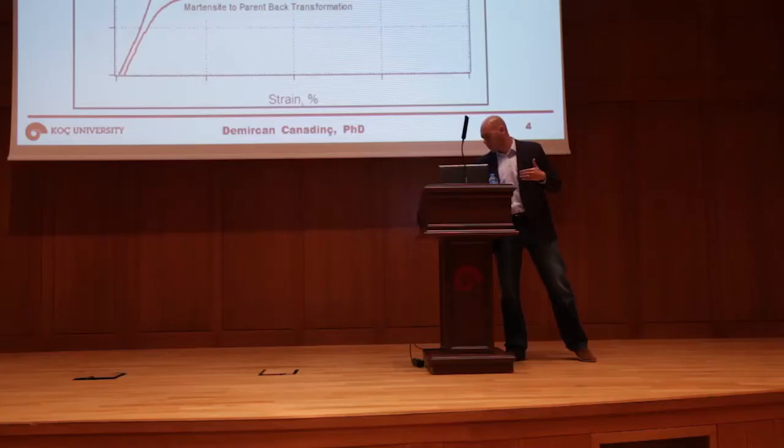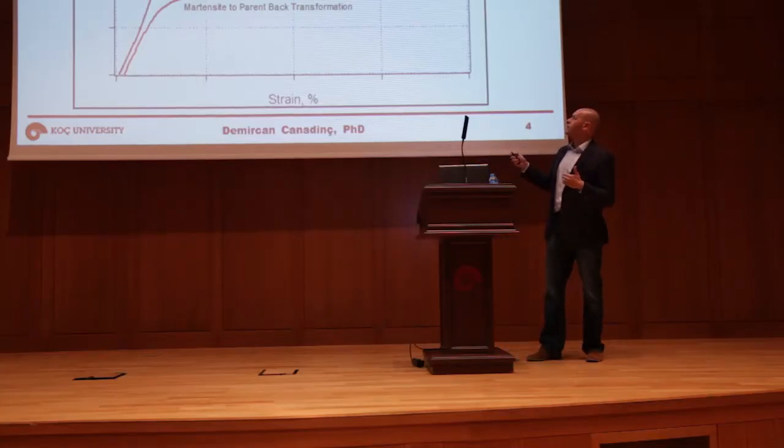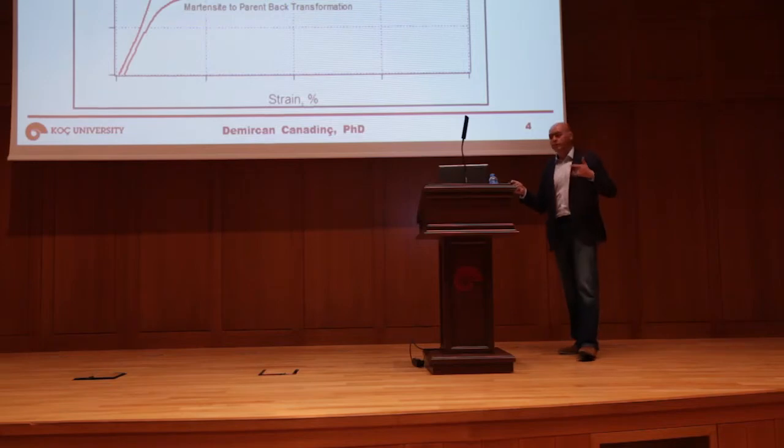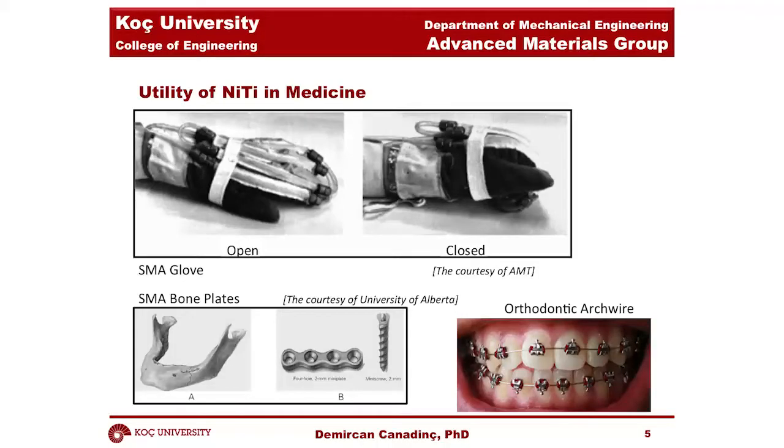However, due to the pseudoelastic property of these materials, that is maintaining a constant level of stress or load, we can actually do this. And NiTi, that is nickel titanium alloys, have been used in this application quite successfully for years. A similar application, maybe even more known to you, is the orthodontic arch wire application.